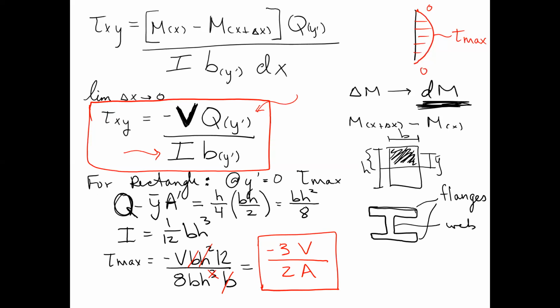And if you're going to calculate Q, say you want the maximum stress, which we know is going to happen at the centroid, so we're looking for that to be our A prime. You're going to calculate Q.